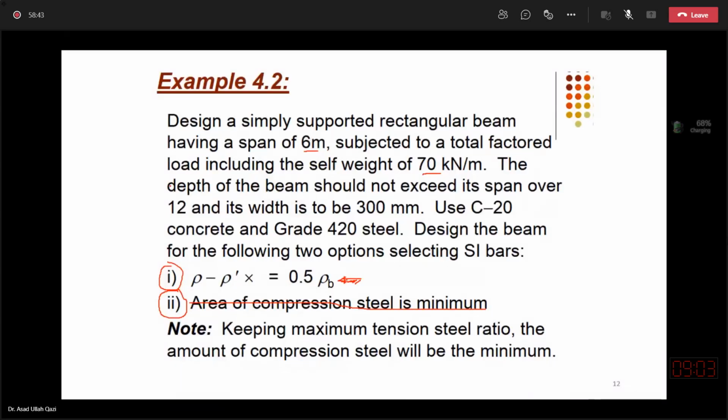And don't forget that when beams are having some cross sections, when you estimate the load transferred on the beam, we did that estimation in the last lectures, and we divided the slab into trapezoids or triangles. What we were calculating was the weight of the slab only. What was the slab dimension, and what we did the calculation, that does not include the stem load, the projection of the beam below the slab.